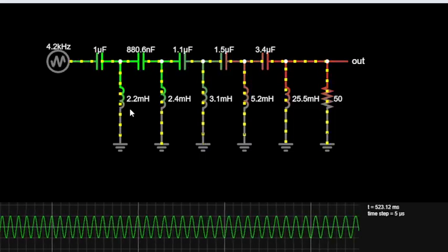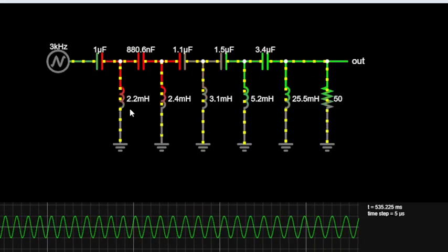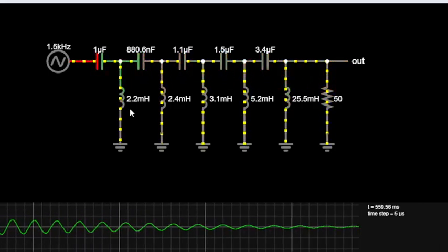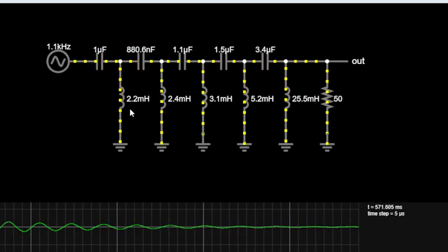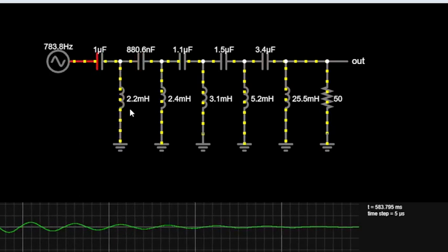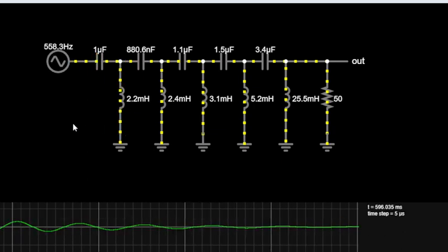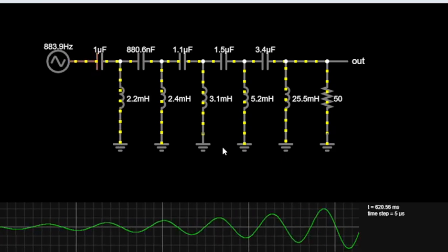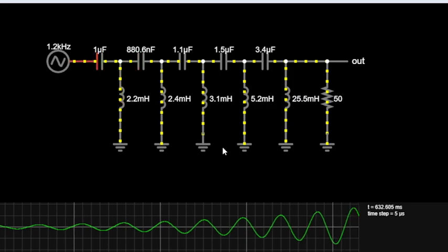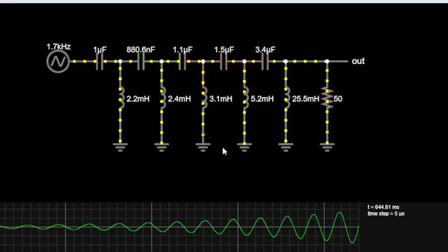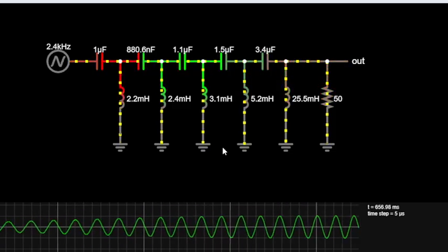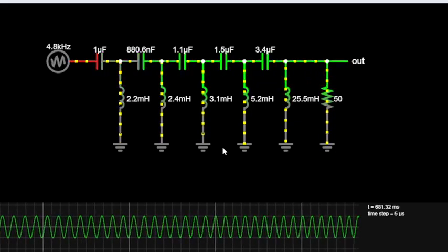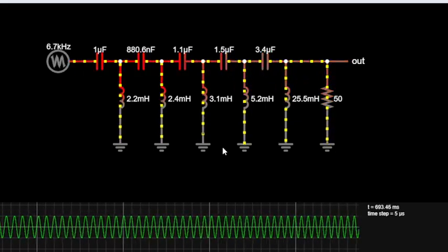Let's discuss a little bit of the characteristics of a high pass filter. It allows frequencies above a certain cutoff point to pass through while attenuating frequencies below it. This 10 pole Butterworth filter is exceptionally efficient in achieving this, providing a steep roll off beyond the cutoff frequency. Looking at the mathematical insight, let's briefly touch on the equations behind the Butterworth high pass filter. The equation for the cutoff frequency and the transfer function might look complex, but understanding these helps in designing and implementing this filter in various applications.